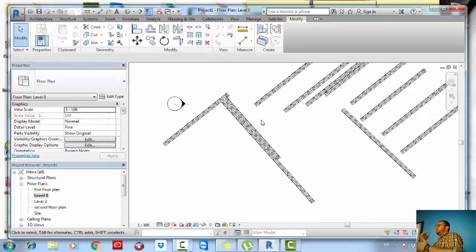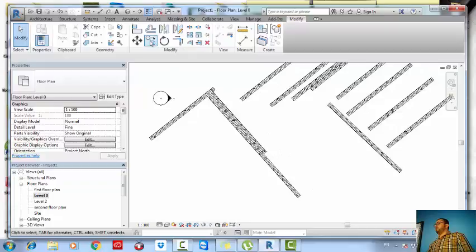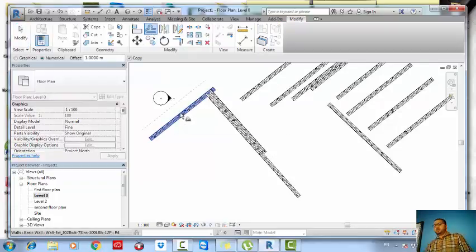What does offset do in AutoCAD? It always copies for a certain distance, and it will always be parallel, and you don't need to draw the path or the value every time, right? Just click on offset or select any object. You can do it. Click on offset. I want to offset this wall. Before you offset this wall, you need to add a value. You need to input a value, right? Just insert your value here on the ribbon.